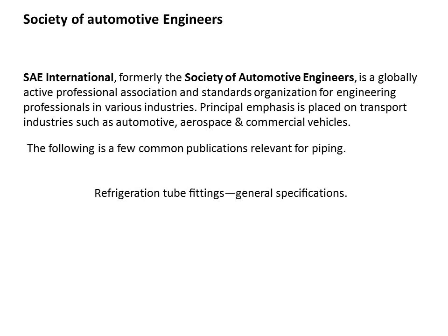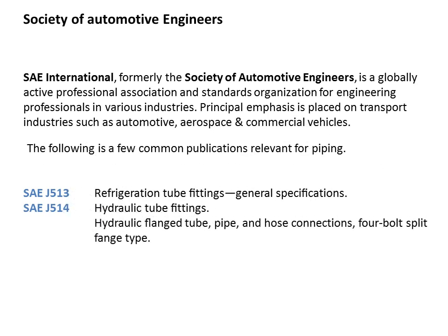One amongst them is refrigeration tube fittings, general specifications. It's covered in SAE J513. For hydraulic tube fittings, the SAE J514 standard is there. For hydraulic flange tube, pipe and hose connections, four-bolt split flange type, we have SAE J518.